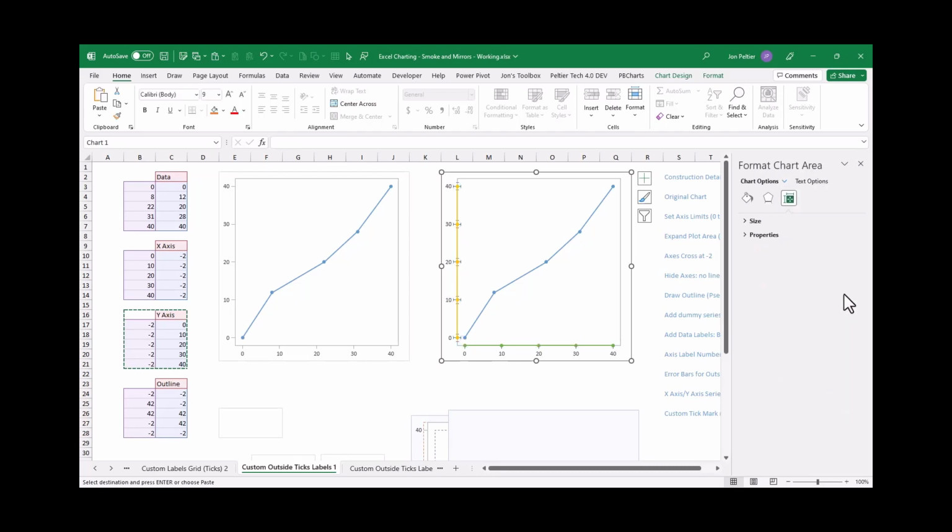So we'll delete those. And now I'll come up here and I'll select the Y-axis Y error bars, which I don't want. And now I'll select the Y-axis X error bars. And I'll format those the same way. So I'll go minus, and I'll say no cap, and a fixed value of 0.